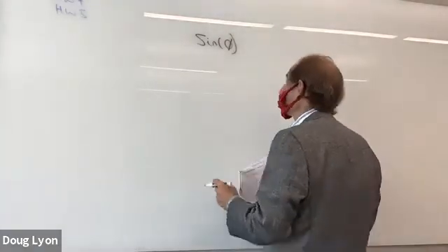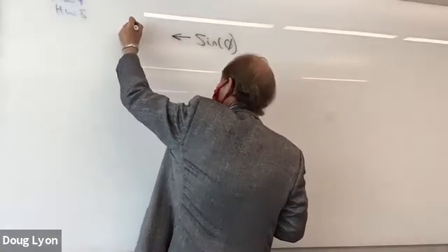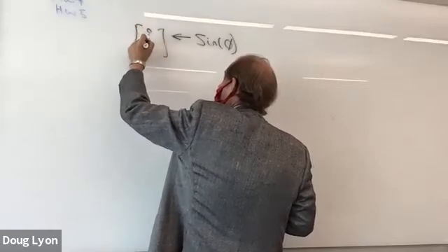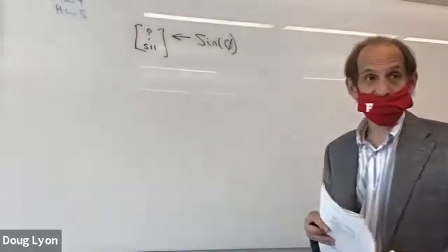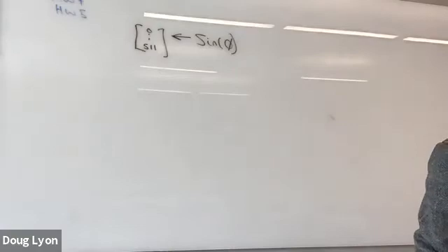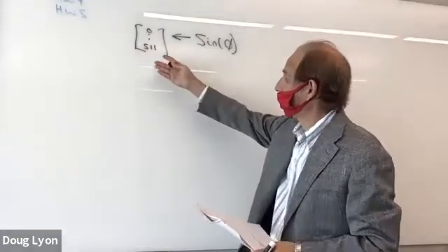So what I'll do is I'll take the sine of theta and I shall digitize it into an array of 0 to 511 locations. I choose this because even if I use 16-bit quantities, I'll be able to have a wave table that can hold an array of 511, let's say, short integers. And I'm going to store the sine table in there somehow.